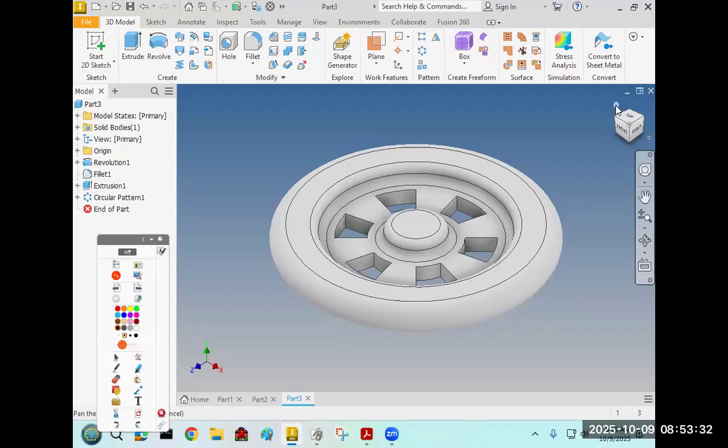All right, so first click on the center point. And then second click on one of those 30-degree lines right there, it's fine, but not on the edge, just somewhere. And then second click on the other 30-degree line. Okay, get dimension, and dimension that green line, so don't go off to the side somewhere below. Somewhere over there, that's fine. So that should be 0.375.